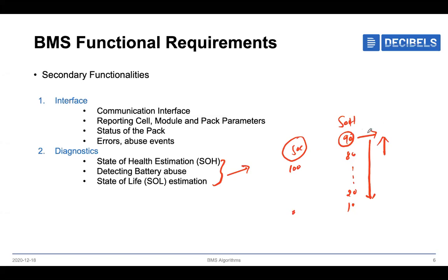So when state of health is 90 percentage, how is the cell behaving, or how are the electrodes behaving? Based on that, they are collecting the data and trying to develop models called neural network models or data driven models, and implement these data driven models into a BMS. As time goes on, as we use the vehicle and the battery pack, our SOH will be decreasing, and based on SOH we can predict how the range of the vehicle will be affected, or how the SOC properties will be affected. But research is still going on in this part.